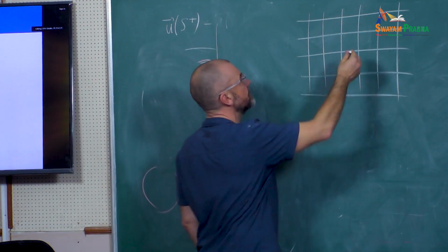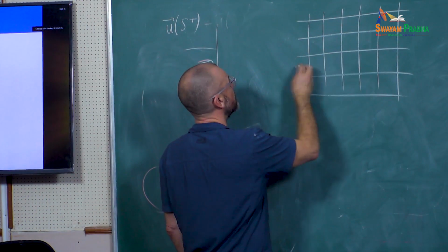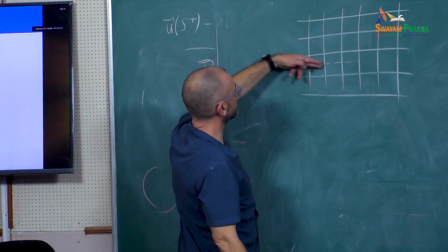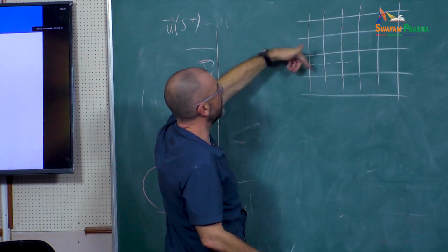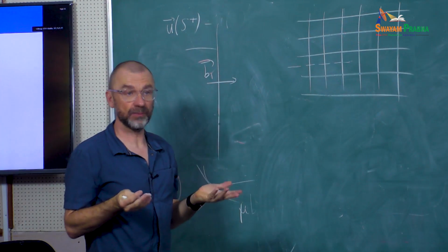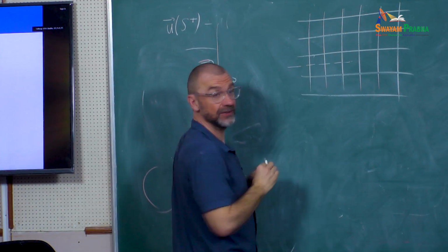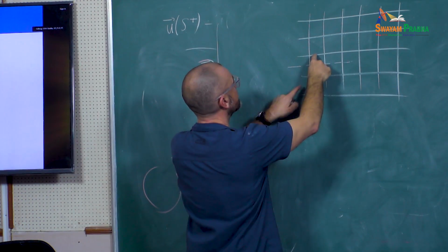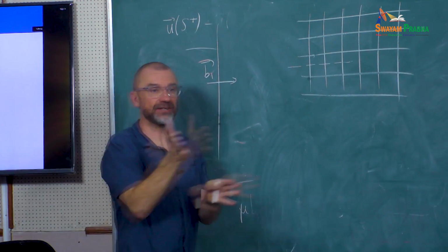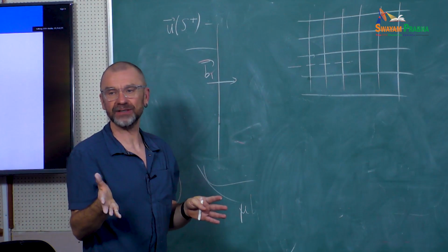So if I want my edge dislocation to be here, the cut surface, for shear, is going to be horizontal. So here I cut with my magic knife. I cut the bonds, and then I move the top part with respect to the lower part by the Burgers vector. Now, if I use a small vector like just this, what is going to happen is that these two atoms will just be a little bit sheared. If I relax, the crystal is going to go back, right?